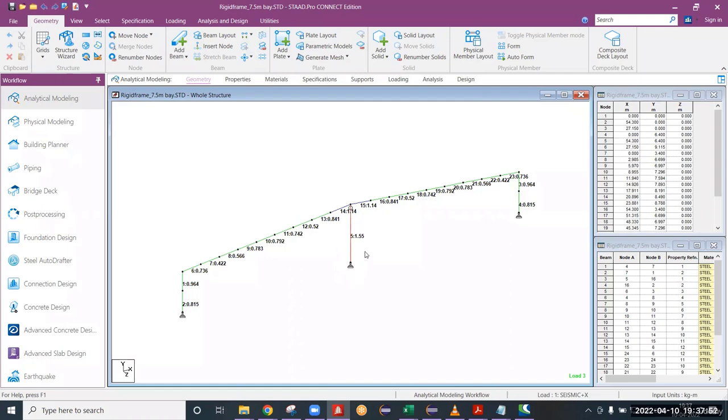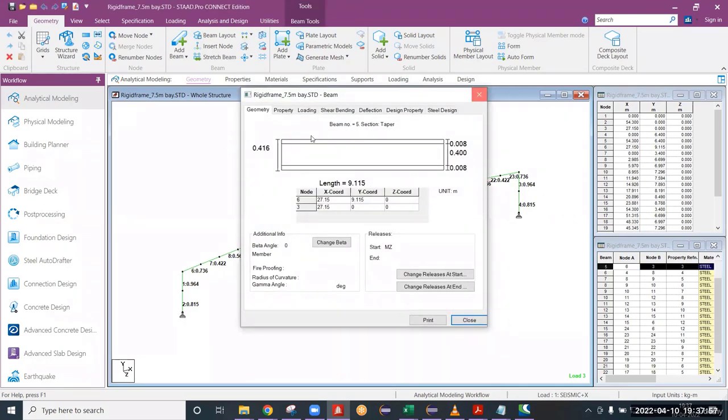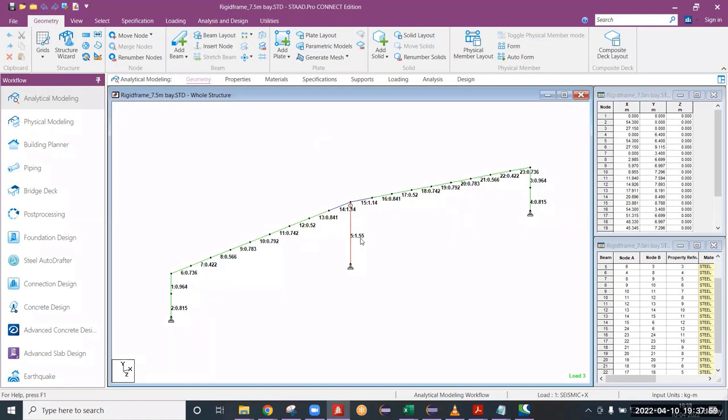Though there is not much difference in the ratio because this length is more. Actually, 9 meters is a lot. 9 meters practically is approximately 3 floors height, right? So the column is that much unsupported. That is why it is failing in buckling anyway. Actually, the ratio can be reduced if we release here. That is how it works. Now let's see how we can optimize.